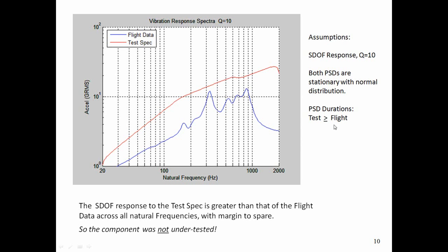And there's ways of looking at flight data to come up with a number of what the effective duration is. You can imagine a multi-stage launch vehicle undergoing some coast periods, and during the coast periods the vibration levels would be negligibly low, and most of the vibration actually happens during liftoff and the first stage burn. Although in this case, I will give you some background that this launch vehicle also had a re-entry event where the vibration level was significant. But anyways, we are tentatively making these types of assumptions here.